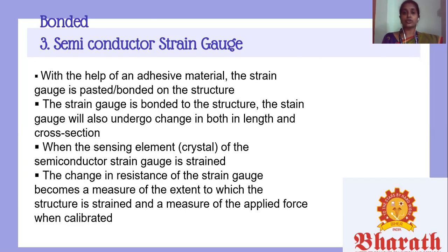Now coming to the advantages of the semiconductor strain gauges. These gauges have a high gauge factor and hence they can measure even very small strains. They can be measured by very small stress. They have a good frequency response. They have a good lifetime. Now coming to the limitations of the semiconductor strain gauge. These gauges are brittle and hence cannot be used again and again. The gauge factor is not constant. These gauges are the most costly and are difficult to bond onto the structure under study. These gauges are sensitive to change in temperature.